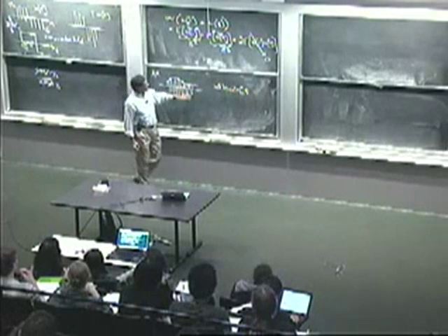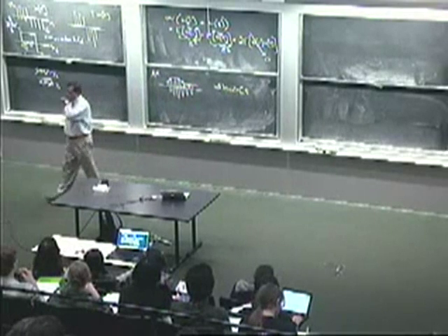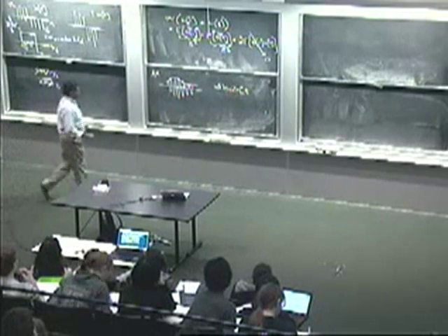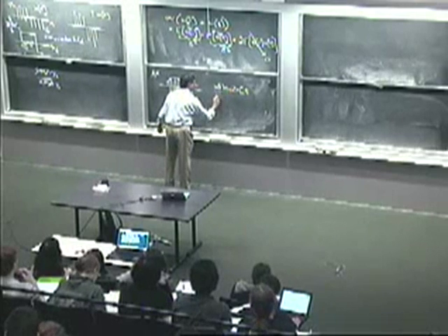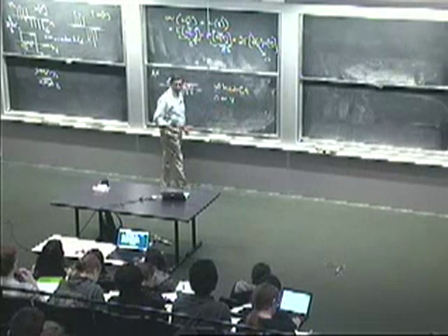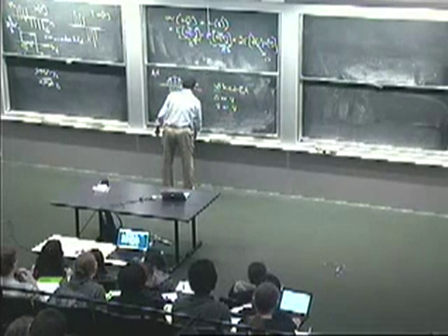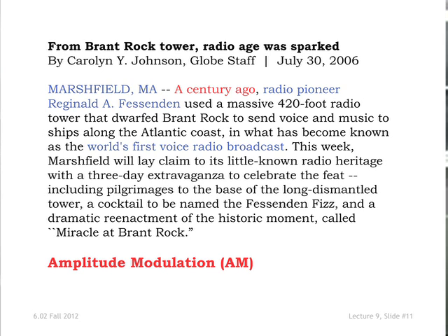So the receiver, what would be done is figure out some way of extracting the envelope here. All right, that's classic AM. Ours is a very simple case where we're saying our x of t is either 0 or V in the case of on-off keying, or it's minus V or plus V in the case of bipolar keying.